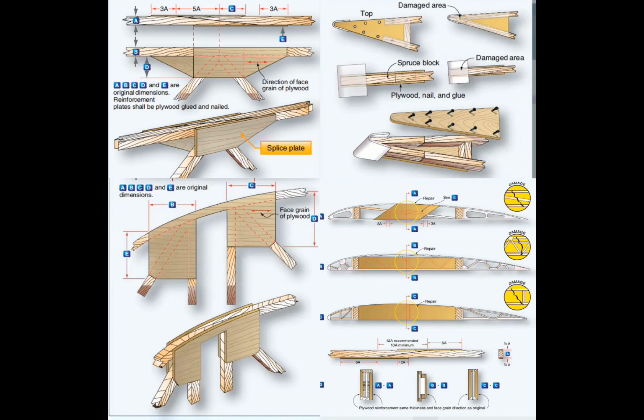Are mineral streaks acceptable in aircraft wood? Yes, if there is no decay. How do you inspect for decay rot in wood? Visual, odor, tapping, probe, prying.